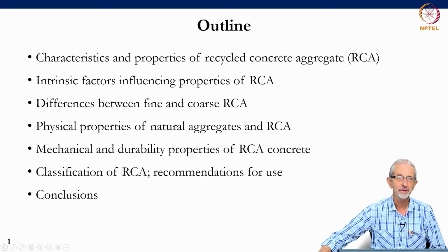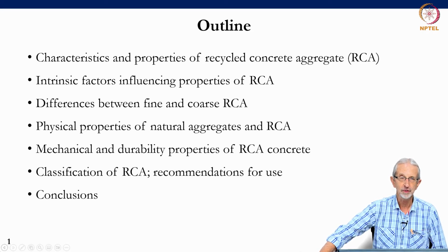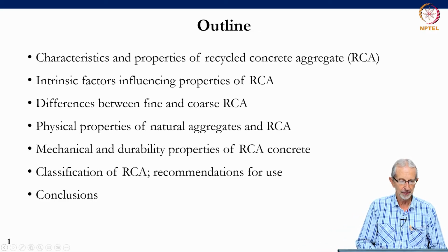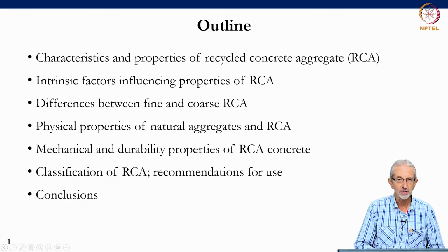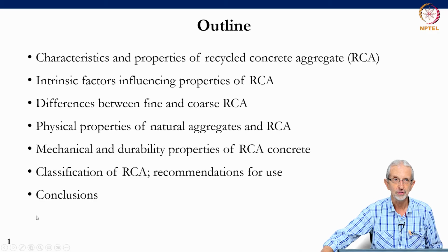And this is what I would like to cover. Some characteristics and properties of recycled concrete aggregate, intrinsic factors influencing the properties of recycled concrete aggregate, or RCA, differences between fine and coarse RCA, physical properties of natural aggregates and RCA, mechanical and durability properties of RCA concrete, and then something on the classification of RCA and recommendations for use. And finally, we'll draw a few conclusions.